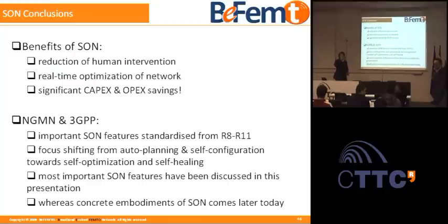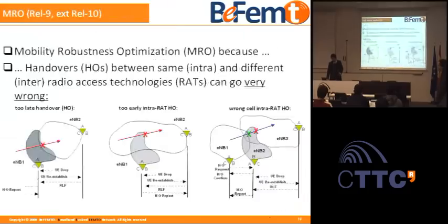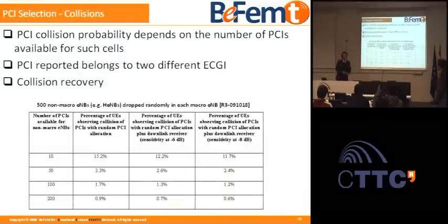Thanks for your talk. It was very nice. I have a question about the PCI collisions that you talked about. I think the problem is not that simple, because when you have this time-frequency grid, you have to, of course, put pilot symbols in there, and you have to know the positions of them a priori. And right now it's done with the PCI. So you know the PCI, and then you know the location of where they exist. And you have only very few possibilities, because they're cyclically rotated every 6 resource elements. So there are only 6 possible positions, actually. So people will have to think about not just moving away from PCI, but completely rethinking the air interface, I think. So it's probably not a question from me, but just an additional statement.